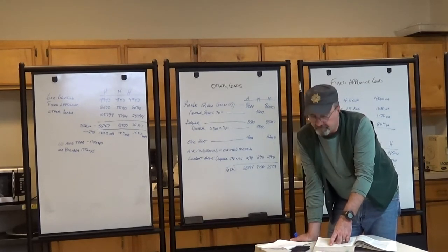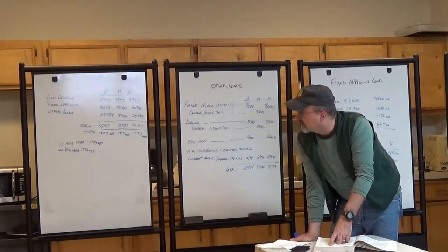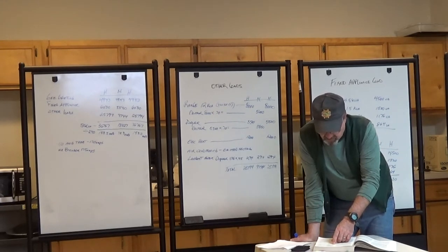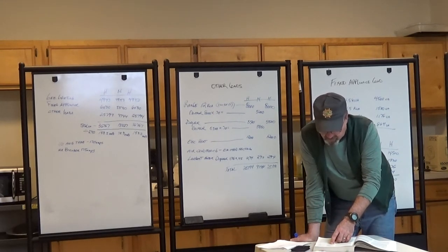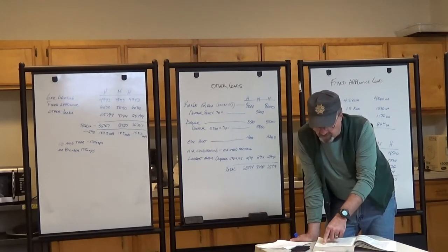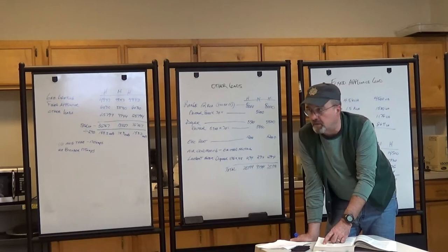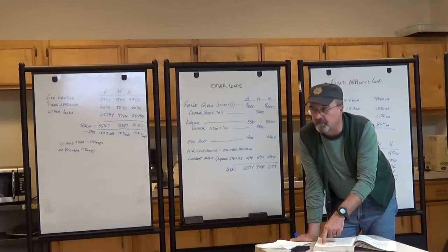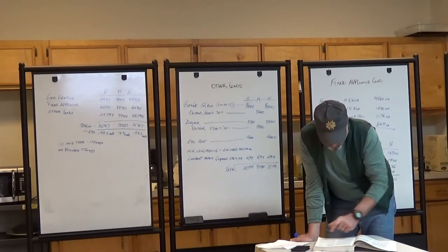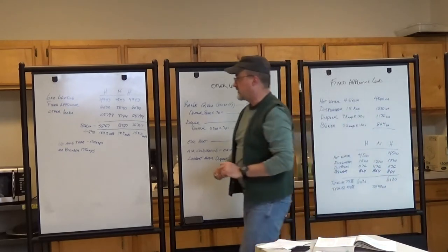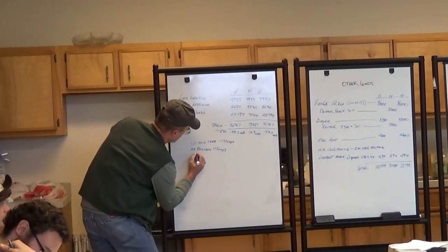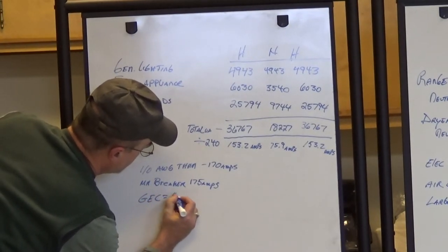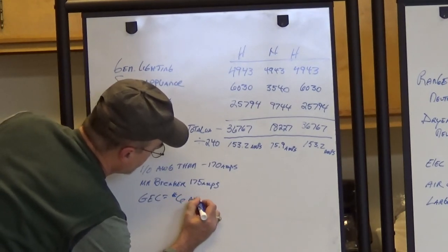That's our hots, right? So what is the size of our hots? 1-aught, right? So for number 1 or 1-aught copper, and we're going to use copper grounding electrode conductor, it doesn't have to be any larger than number 6. Okay, we can use a number 6 wire for that. So that's number 6 grounding electrode conductor. Grounding electrode conductor equals number 6 AWG.